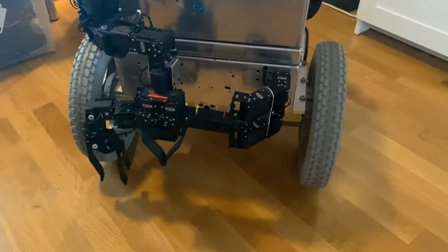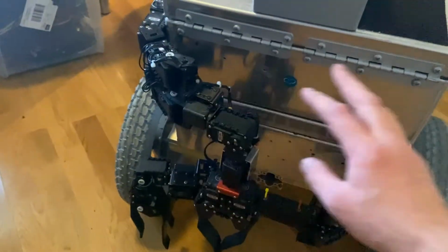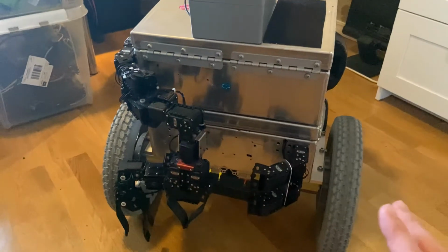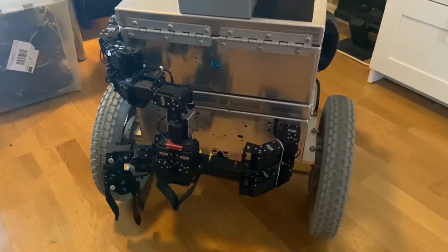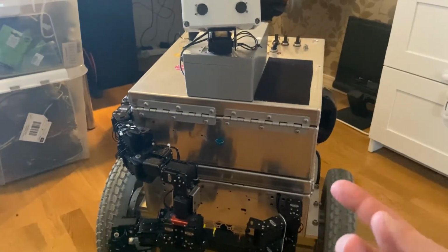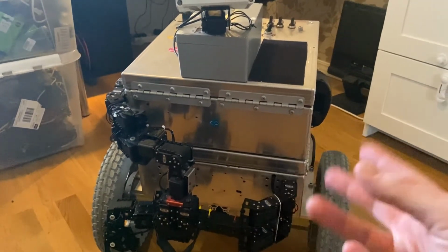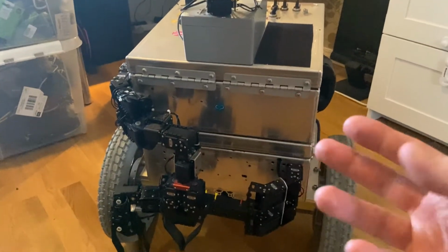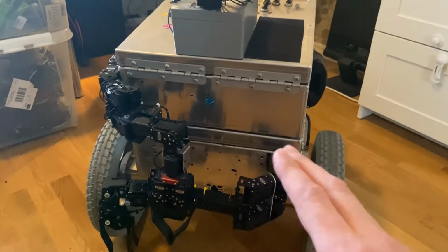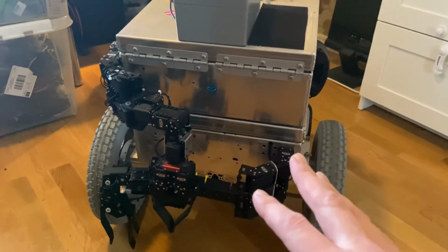One of the biggest tasks has been to replace ROS completely. I had ROS nodes running on individual Raspberry Pis for each of the arms, the wheels, the neck, the vision, everything. But the latencies were quite bad. You give a command and you wait, and then something might happen. Then you send another command and wait, and it happens faster. I isolated the latency to be too dependent on ROS.